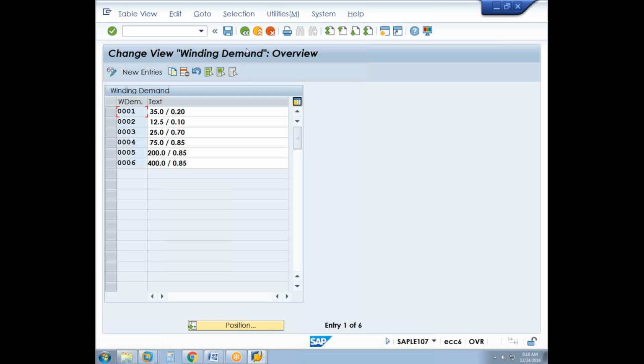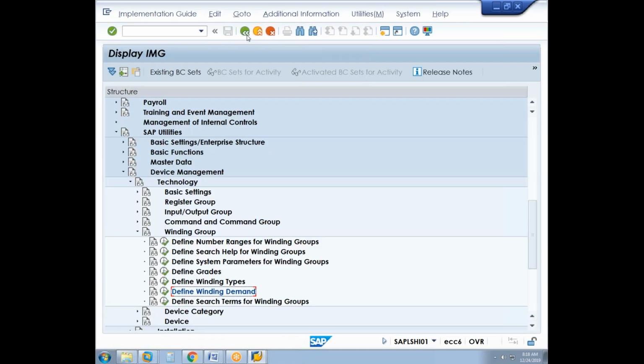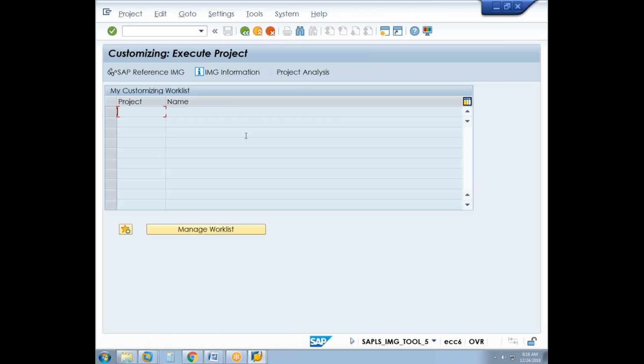So first we will create one winding group for a transformer, which is a low voltage current transformer. In the case of a low voltage current transformer, voltage is not an issue. It is the same as the device specification, but the current is different. That means 200 amps, where we expect the transformer output to be 20 amps, because that is the specification of the meter.